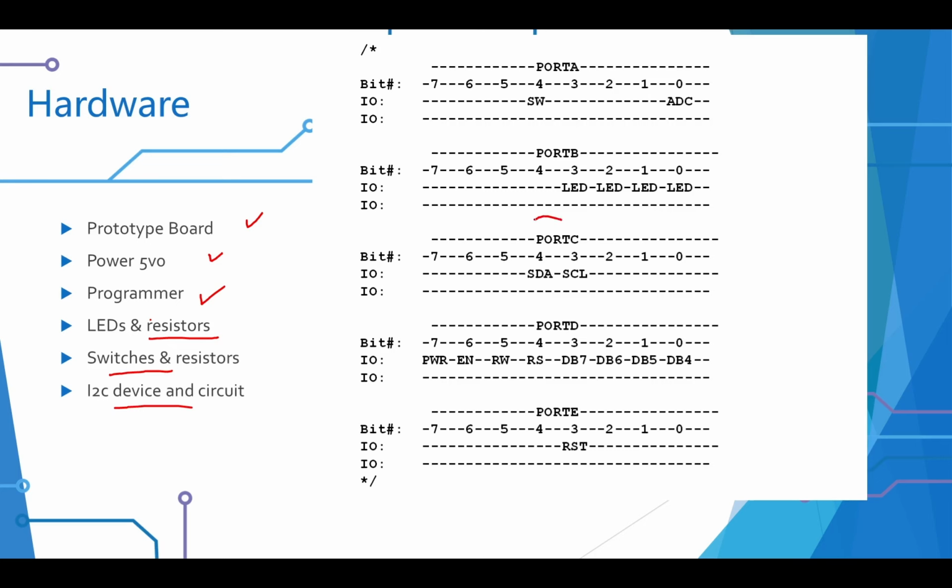Now, I've got the data SDA hooked up to port C4 and C3 for the clock. I've also got, and it should be very clear here, a transmit on here. There are other LEDs and other things, but those are the three things. It's C7 for transmit, C4 for data, and C3 for clock. We need those in our brain because otherwise it won't work.